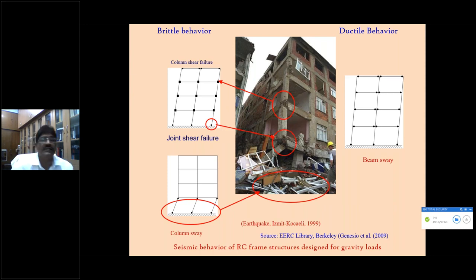you may experience, like say, the dark points here, when earthquake forces are acting. You experience the critical region between the beams and the columns, the joint, will experience plastic hinges. The plastic hinges will be formed at the junctions of the beams and the columns. That is a very important issue that we can deal with separately, but now that is just for understanding.